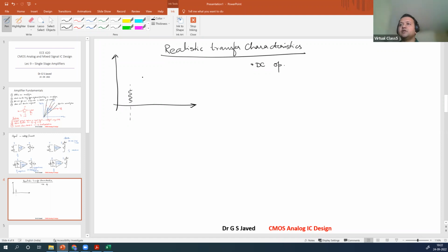if you give the voltage, now depending upon where you are taking the output, if you are on the higher side, if you have an equation like this, where you are on the higher side, your voltage can start clipping like this. This is called high side clipping.